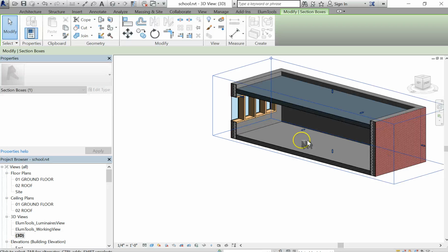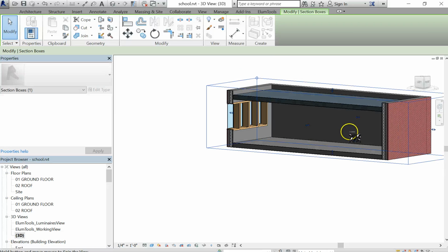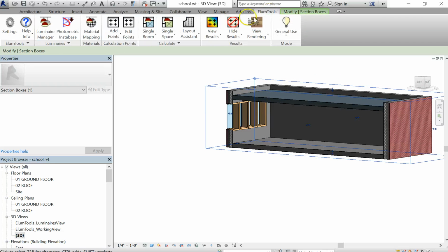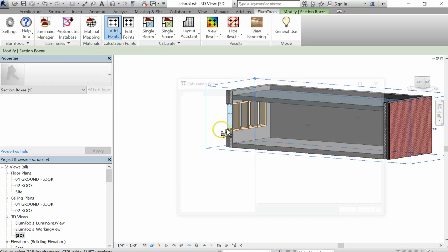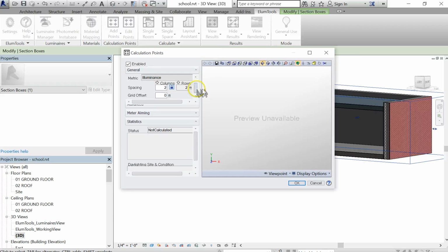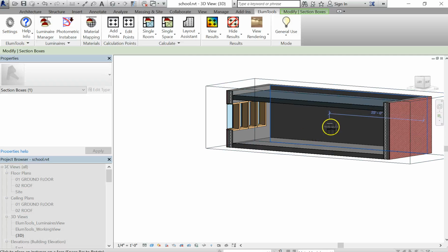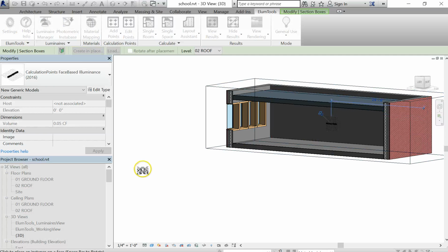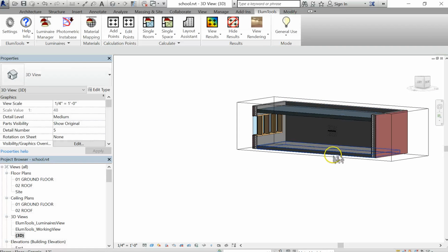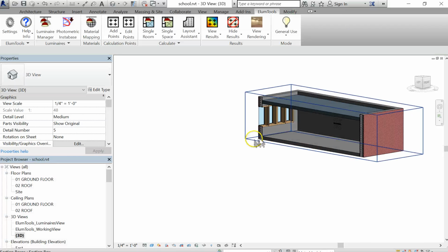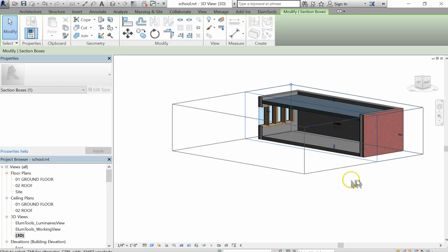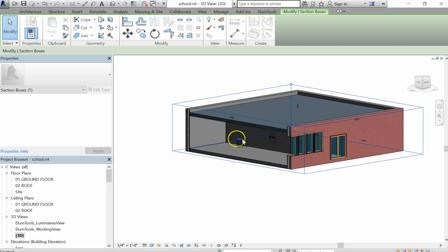And then I'm going to cut it a little further in, and I'm going to do this wall in here. You'll see right when you click this, I kind of snap through this very quickly. But it's very similar. It has the same spacing, 2 foot by 2 foot spacing. And in this case, we're not offsetting off the wall. We want to keep it at 0 feet, so it's placed right on the wall. Hit OK. That little family shows up again, and you click on the face that you want it on. Alright, so we have 2 planar faces and 2 rooms marked with analysis points.